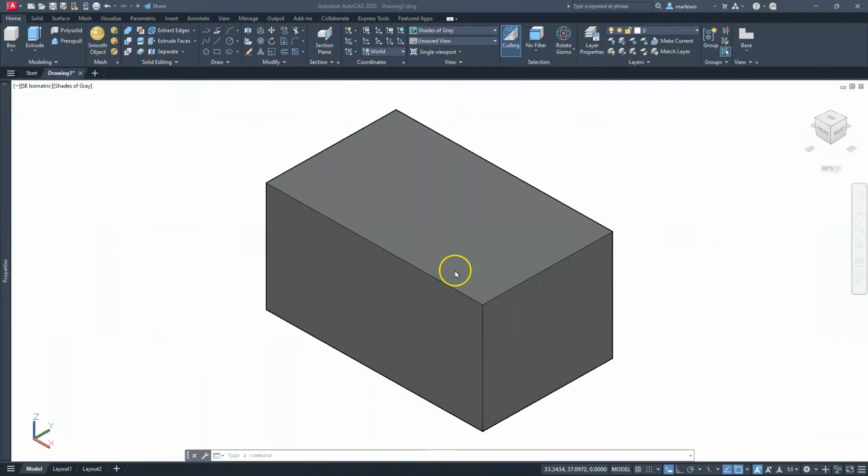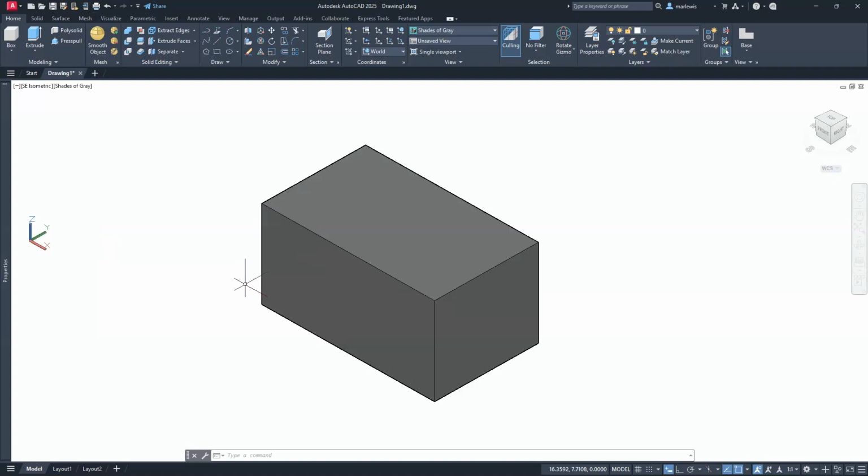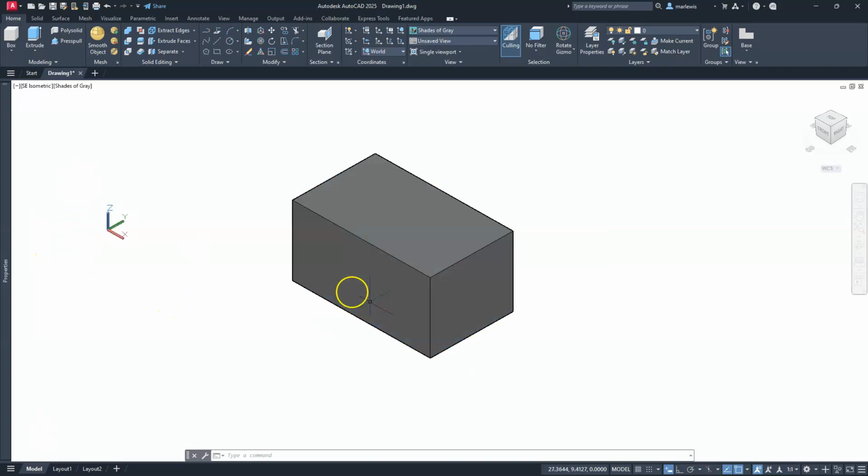Okay, so here in AutoCAD, what I'm doing is just starting off with a block, right? Now, I could have created this block in any form, but if I wanted to create something else on here, if I want another angle and then I want to extrude into this, you can see that I can only create things on the X and Y axis. So you have to understand that that's going to be the most important thing. So if I zoom out a little bit and put a regular rectangle here, you're going to see that it's going to create that rectangle along the X and Y.